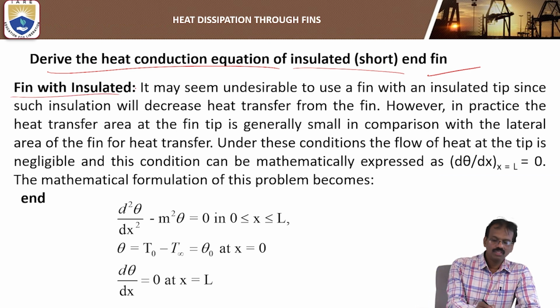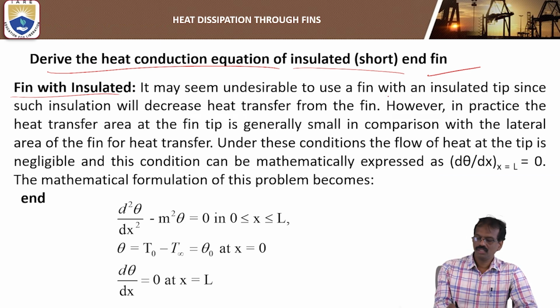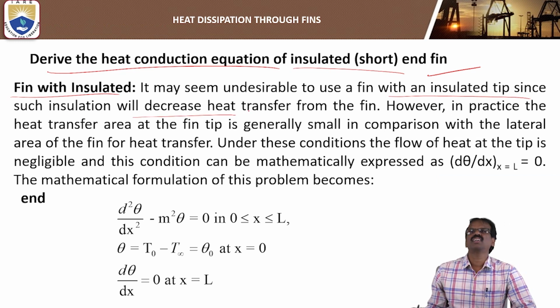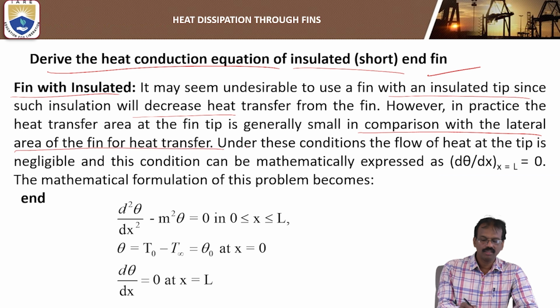It may seem undesirable to use a fin with an insulated tip, since insulation will decrease the heat transfer from the fin. However, in practice, the heat transfer area at the fin tip is generally small in comparison with the lateral area of the fin.